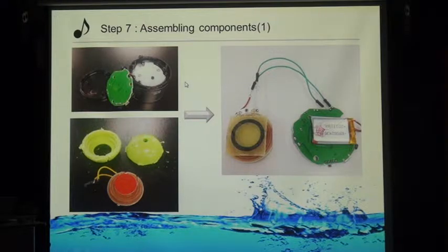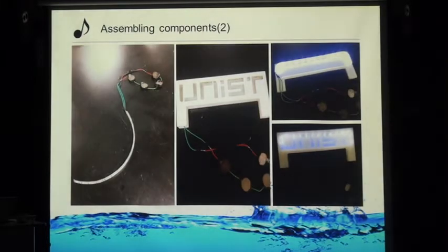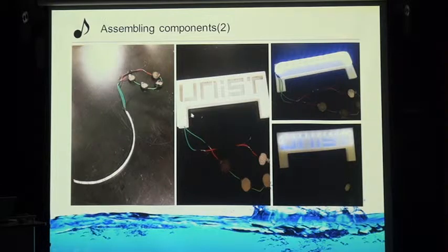We wanted to make the speaker with a Bluetooth speaker and a vibration speaker, but this speaker was too expensive, so we bought each of them, disassembled the Bluetooth speaker and vibration speaker, and connected them using soldering. And this is the LED part. We had a 12-volt LED, a waterproof LED, and four 3-volt batteries. So we connected them in series.